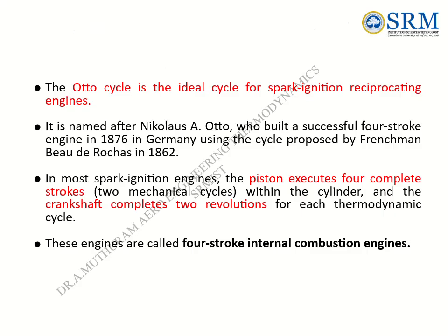It is named after Nicolaus A. Otto, who built a successful four-stroke engine in 1876 in Germany using the cycle proposed by Frenchman Beau de Rochas in 1862. In most spark ignition engines, the piston executes 4 complete strokes, 2 mechanical cycles, within the cylinder, and the crankshaft completes 2 revolutions for each thermodynamic cycle.